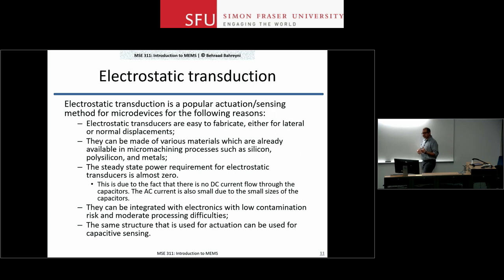And in terms of design, you can have symmetric designs. The same design that you use for actuators, you can use it for sensors. The combs that we saw before that improve the capacitance or dC over dy, that increase in dC over dy or dC over dx value helps you both on the sensing side or actuation side. So again, it makes the system optimization relatively easy compared to some of the other processes.